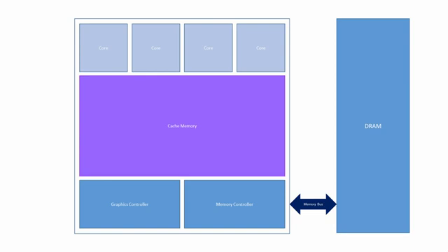Cache memory is much faster than DRAM because of the technology used to build the cells that store individual binary digits. Cache memory cells are flip-flop latch circuits which can be accessed very quickly. They also retain their contents as long as they are supplied with power, which is why this type of memory is known as static RAM or SRAM for short.